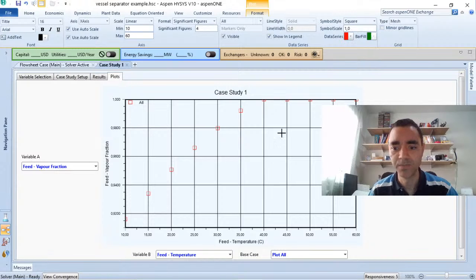But as a safety margin, we choose 10 Celsius degree, and thinking about control of the system, my operating temperature at the discharge of the heat exchanger will be 50 Celsius degree. But if for any reason my temperature transmitter identifies that we reached 40 Celsius degree, we will have an alarm to alert the operator that something is wrong.